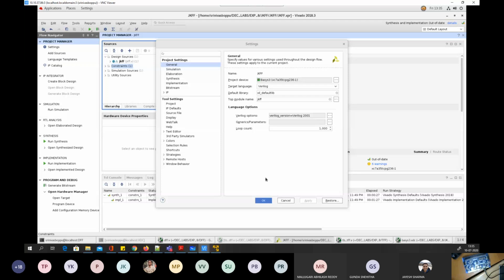But when it comes to Vivado, we need to use either these switches or these LEDs. Generally we'd use the clock available here, but it's 100 megahertz, so we won't be able to see anything on the LEDs. So we use this button, simulating the passage of the clock. If the button is not pressed, it's 0. When you press it, it momentarily goes to 1, and as long as you press it, it stays at 1. That's how we simulate the clock here.